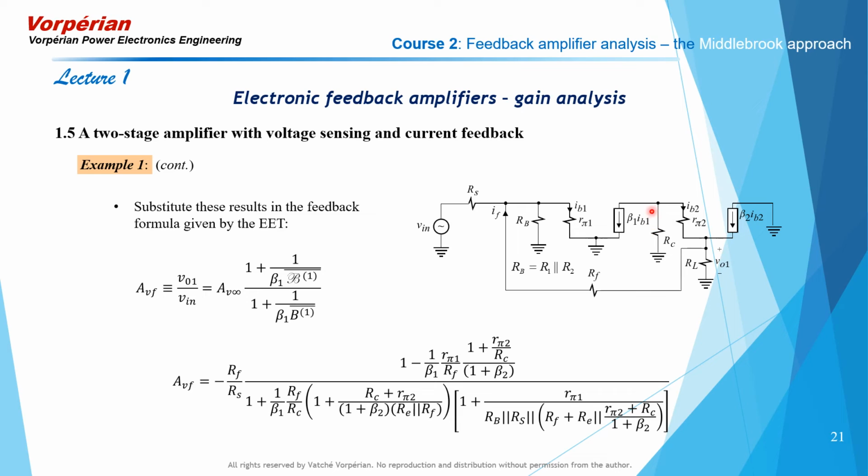Now, if the gain of the amplifier becomes very large, then the dominant path of the signal from input to the output is through the main amplifier path, and its gain is controlled by the feedback connection. That's when you have feedback. You have feedback action when you have large gain in your amplifier around which you're applying the feedback. The feedback action dies when the gain of the amplifier goes to 0 or very low. The feedback connection nevertheless is there, but it can no longer be called feedback.